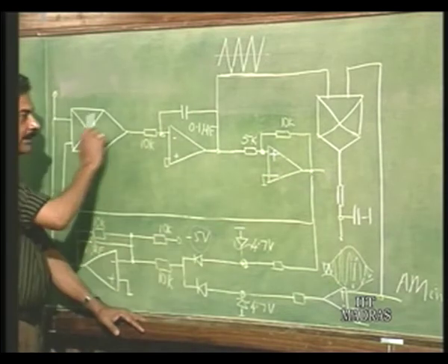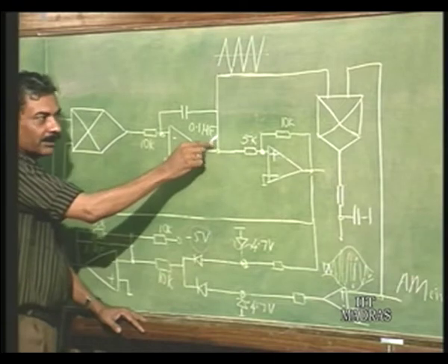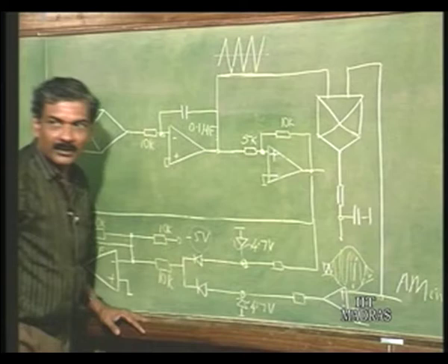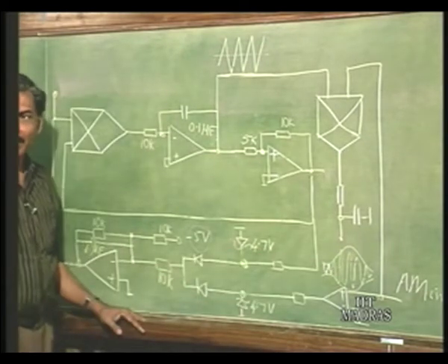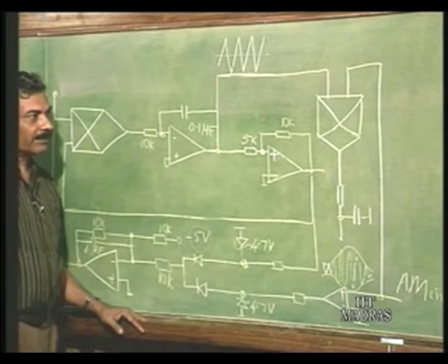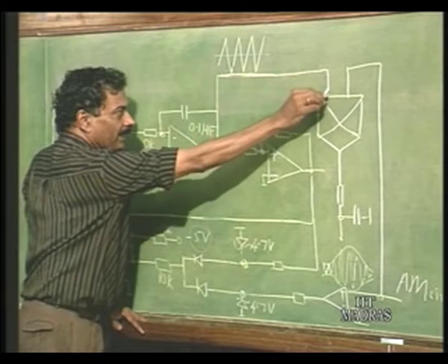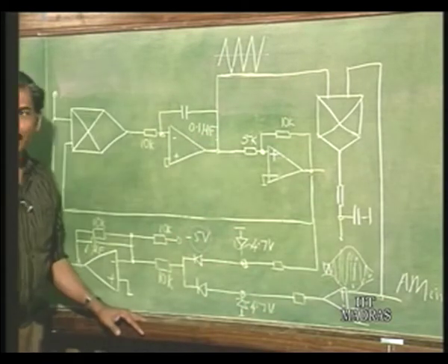That is already done by this VCO here, that is an integrator. If you take the triangular wave output, this will be in phase with the incoming sine wave or this particular carrier. Okay. So, this part of the experiment we will see that if you take the output here, it will be a triangle with the same phase as the incoming carrier.